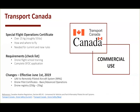And then anything beyond that, any drone over 25 kilograms, flying over advertised events or large crowds, within an airport, or above 122 meters or roughly 400 feet, you're going to have to apply for an SFOC. So those are the three categories that Transport Canada is implementing as of June 1st.